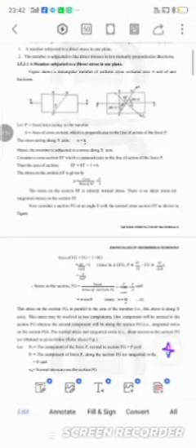Shown in the figure, a member is subjected to a direct stress in one plane. In this plane, the rectangular member of uniform cross-sectional area A of unit thickness, let P be the axial force acting on the member, A is the area of cross-section which is perpendicular to the line of action of force. The stress acting on the x-axis is equal to load divided by area, hence the member is subjected to a stress along the x-axis.